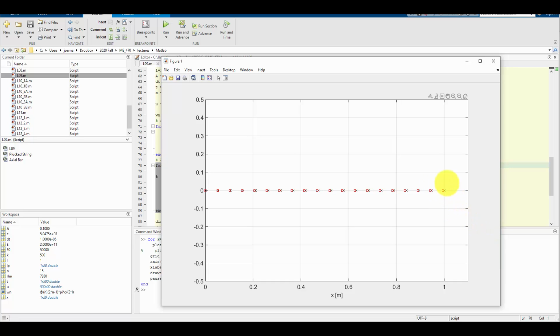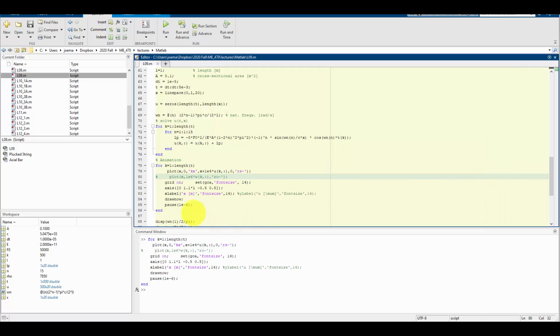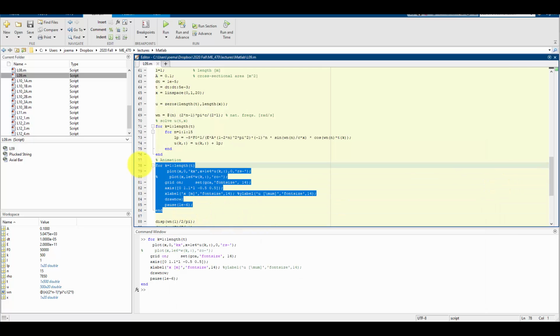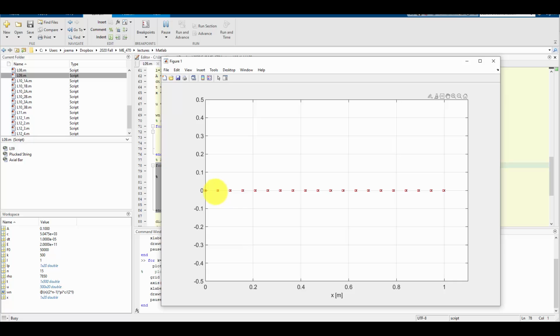And we see that it has more value of u as we go to the right on that free end, whereas the left end is barely moving at all. So looking at it just one more time. We see at the wall, the square doesn't move at all because there is no deflection, and then it moves only a little as we go from that wall to the right, and then there is more and more displacement as we go to that free end of the bar.